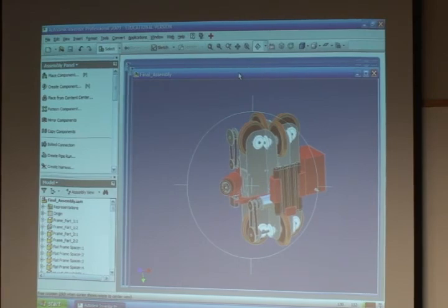There's a lot of little tricks that you could do. My rule was never use set screws, but you always have to. So even though I say never, you always have to use a set screw somewhere along the line. A lot of kids and teams will use just a single set screw. I'm thinking, well, if I put two in there, it shouldn't work loose. You've got less of a chance of it coming loose.